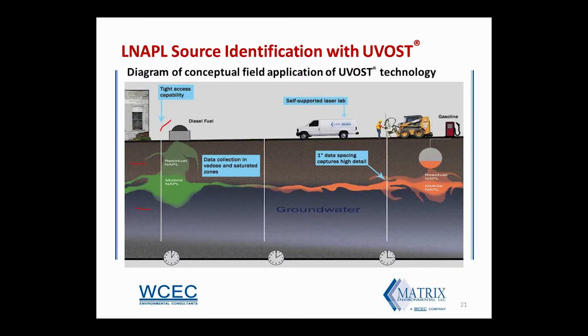The UVOST borings, we typically recommend that they're conducted on a grid pattern across the site. So you can see 3 borings represented here, and we've got the nice little clocks to show you they're maybe an hour apart to do those. And we usually recommend thinking about a 25 to 30, maybe 35-foot grid, but that can vary greatly based on site conditions, the size of your site, and other things that you already know about the site.